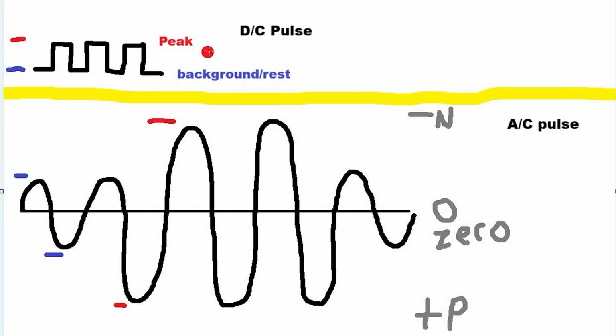The main benefit to pulse is you can typically achieve more penetration with less heat input because, again, on thinner material, the goal is to fully fuse it, but you don't want to put so much heat into it that you start melting through and make a hole. So pulse can really help with that. It can allow you to achieve things that you wouldn't normally be able to achieve, like full penetration with one pass on thinner material, without putting excessive heat into it. So it's pretty sweet in that respect.